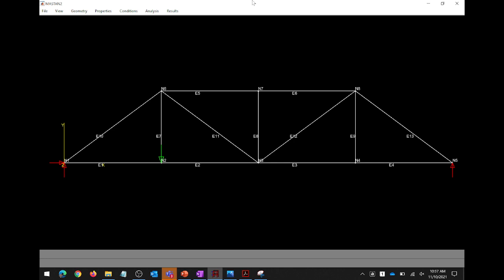Okay, now I'm going to switch it up a little bit. We're going to do some different members. Let's do this member. So that's member AB. Okay, let's do this diagonal. Let's call that CH. And let's do a compression member. Which one you want to do, the left or the right? Left. So that one's FG. All right. Okay, so what I'm doing is I'm placing the load at B, the load at C, the load at D. And what I'm going to do is record the response.